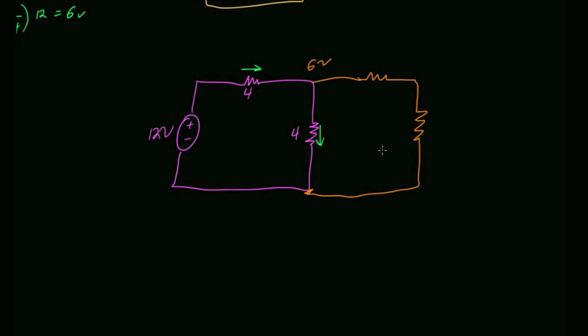With the extra resistance on the circuit, there's less current going through, so there's not going to be as much. There's less current. Right, that's exactly. So there's a couple ways we can think about this. If I slap extra resistors on there, then what's going to happen to the current coming out of the source? More current or less current? Less current. Less current means everything gets smaller. Okay, so that's one way to think about it. Here's another way to think about it. If I put some resistors here, those resistors will be effectively in parallel with this resistor, right? With the 4 ohm resistor.